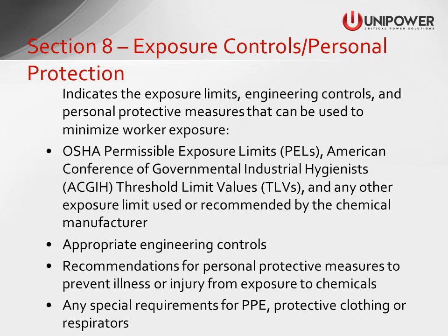Section 8. Exposure controls and personal protection. This section indicates the exposure limits, engineering controls, and personal protective measures that can be used to minimize worker exposure. OSHA's Permissible Exposure Limits, or PELs, the American Conference of Governmental Industrial Hygienists threshold limit values, and any other exposure limit used or recommended by the chemical manufacturer are explained in this section.